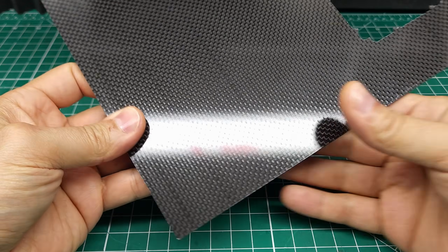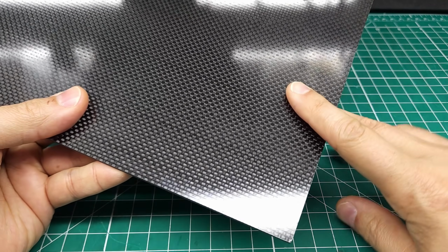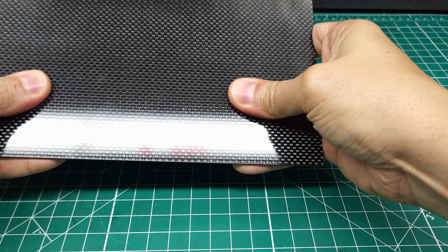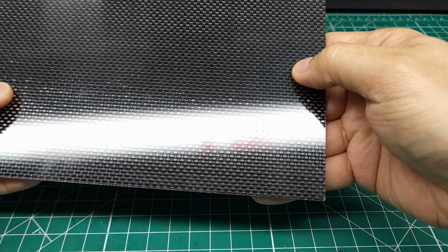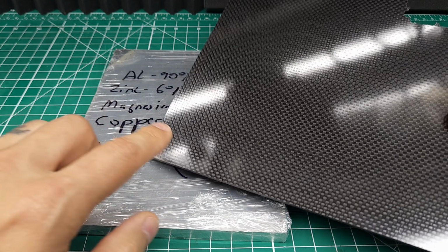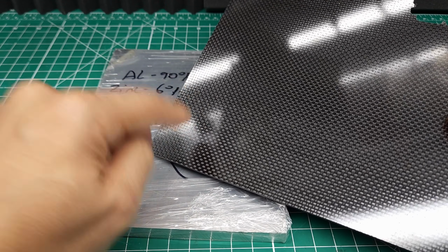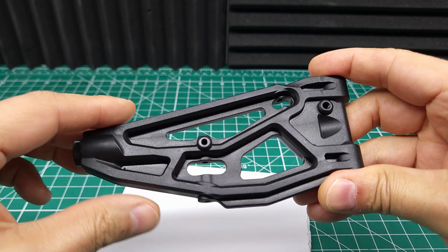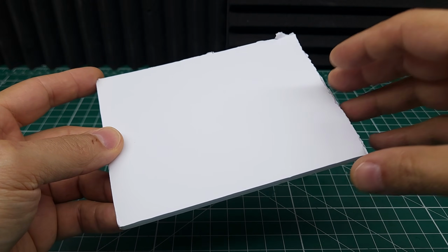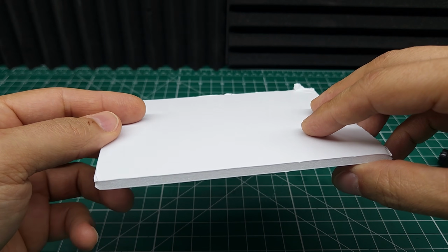Something like this carbon fiber sheet, on the other hand, is a composite. A composite combines the properties of multiple different materials to create a new material. This is primarily carbon fibers with a resin to bind them together. And while homogeneous materials are great, composites can create some properties you just can't get anywhere else. And while there are many different types of composites, this glass-filled nylon being one of them, one of the simplest and most common is exemplified by this piece of foam board.